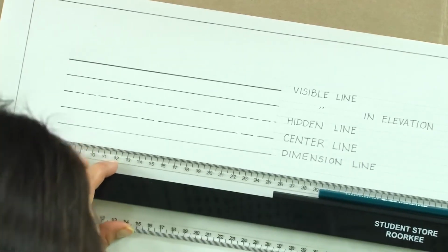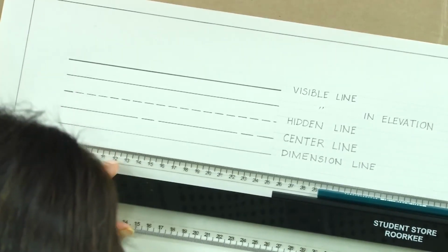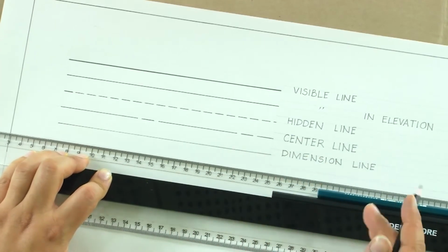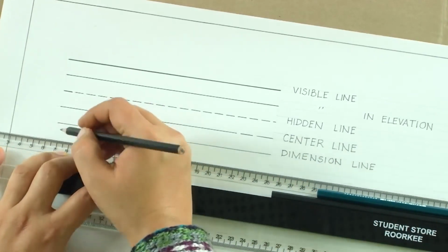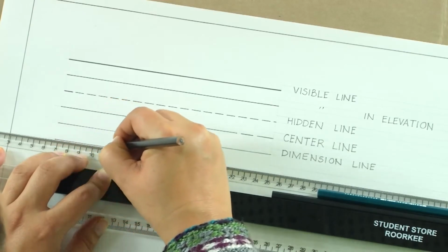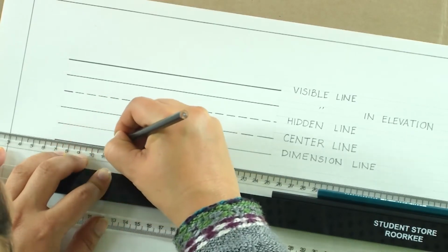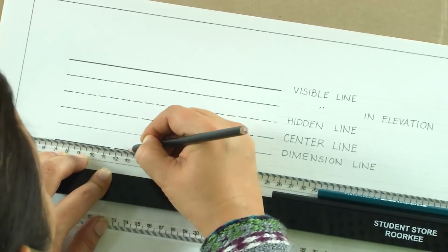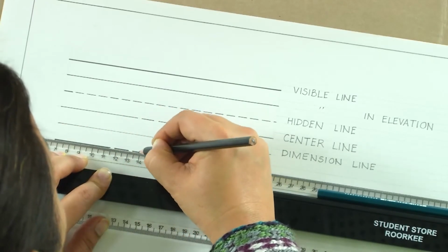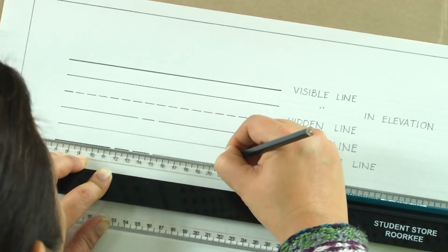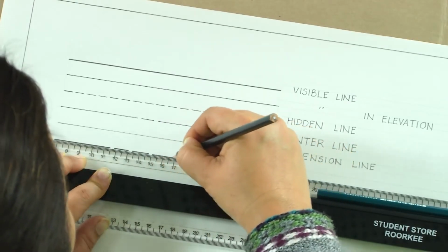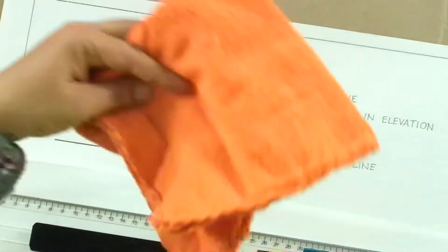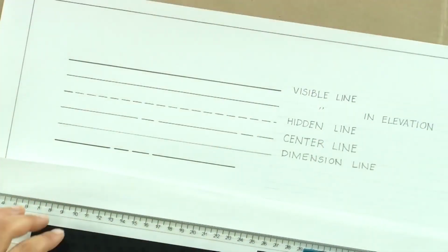Next, we have a section plane line. A section plane line is a very thick line, which is also called a cutting plane. What we have in this one is a thick, very thick line, a bigger dash, then two smaller dashes. It is very similar to the center line, but this is what we use for the cutting plane line.